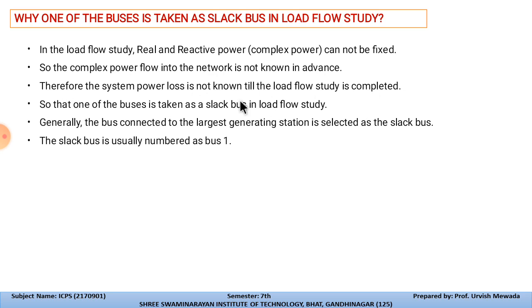Therefore the system power loss is not known, because as we do not know the complex or apparent power, we cannot describe the power losses at the time when we start the load flow studies. Only when the load flow study is completed can we define how much loss takes place in the power system. So one of the buses is taken as the slack bus in the load flow study.